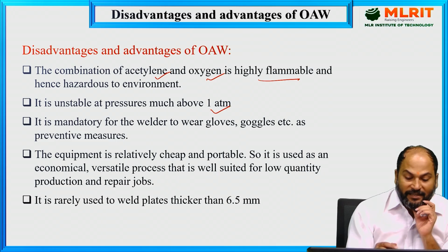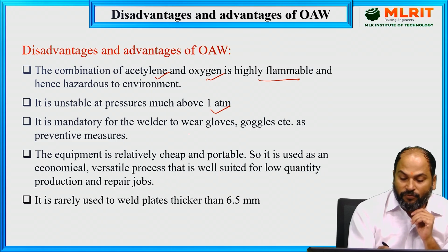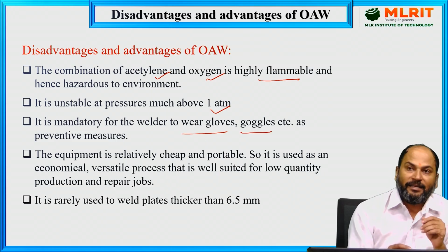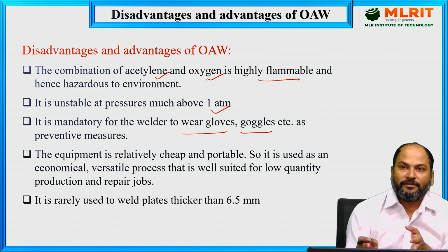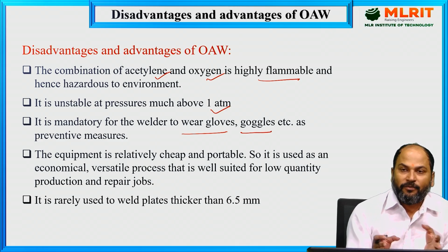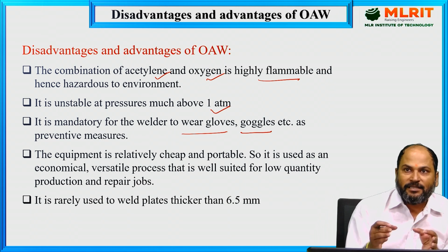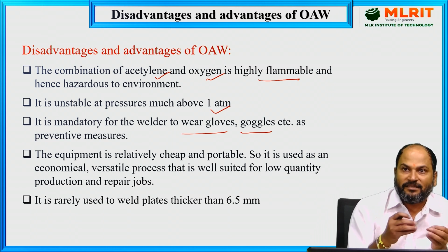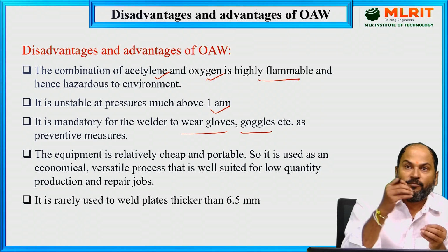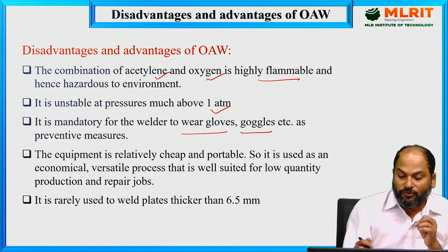It is mandatory for the welder to wear gloves, goggles, etc. It's not like shielded metal arc welding, where granules of flux were there, so you don't need to wear them. Here, as you are using gases and there is a reaction, hazardous fumes will come out. So you have to wear protection.